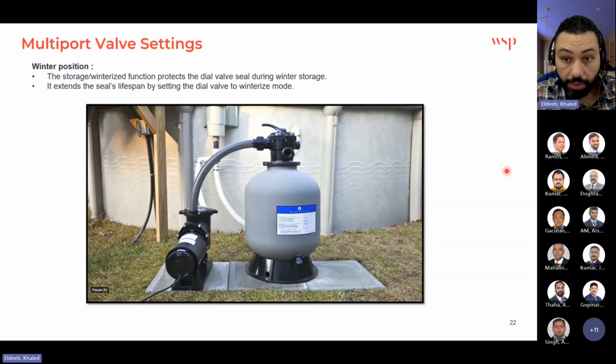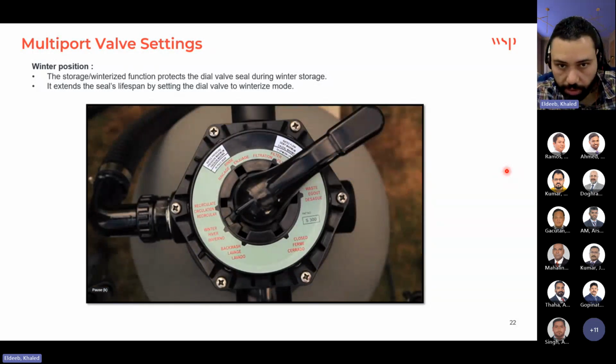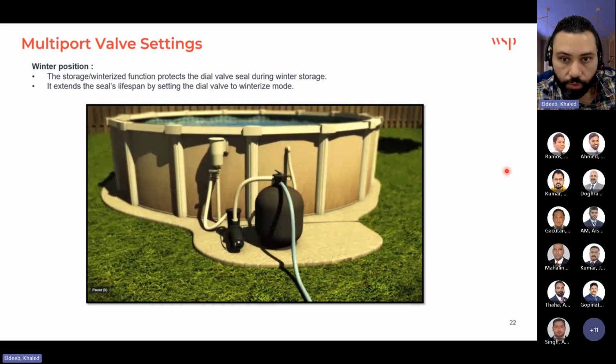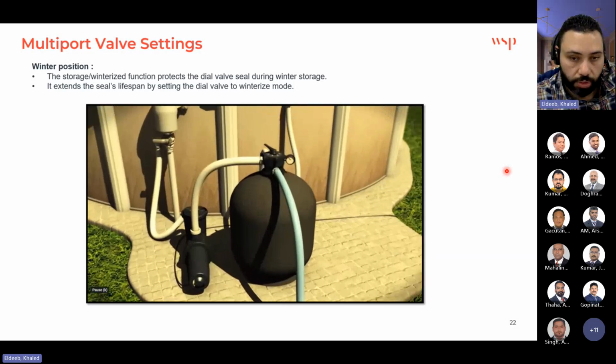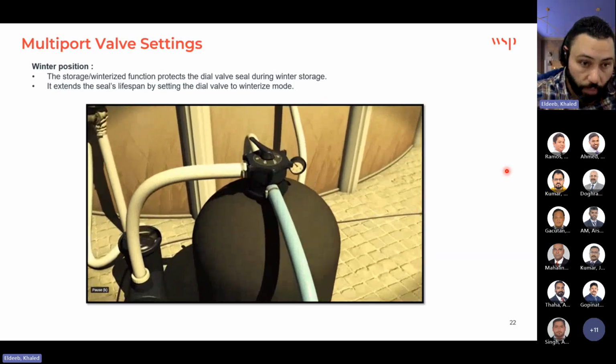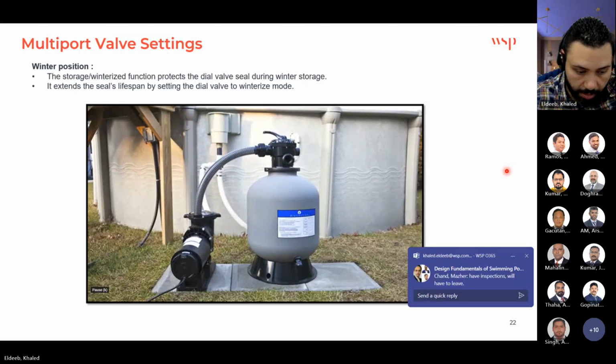In winter, specifically in freezing periods, which is not here in Europe or America, we use this position to increase the seal lifespan while the filter is not used, because if there is water inside this valve, it might expand while freezing.